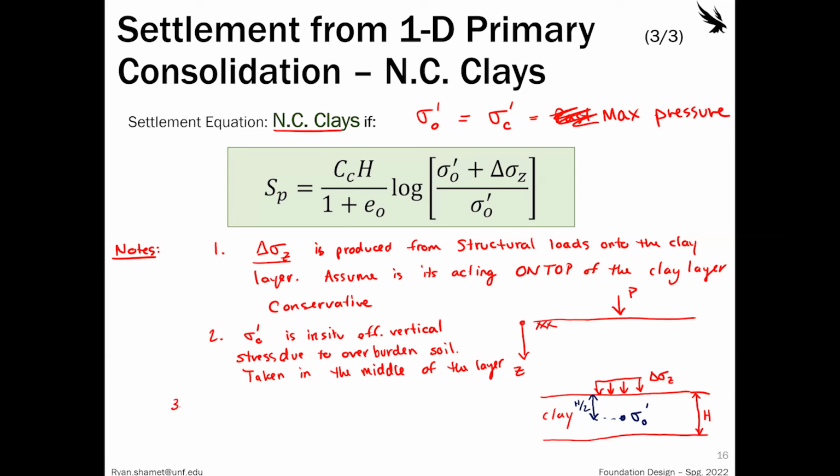Third thing, if the clay layer is large, and generally what large is, we're just going to say is greater than 20 feet in thickness, then you need to subdivide.